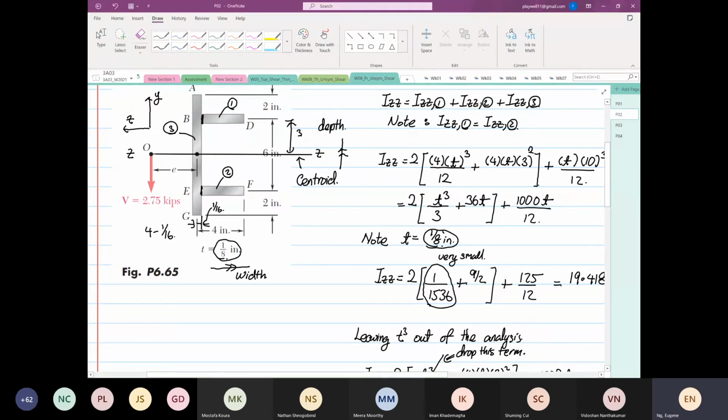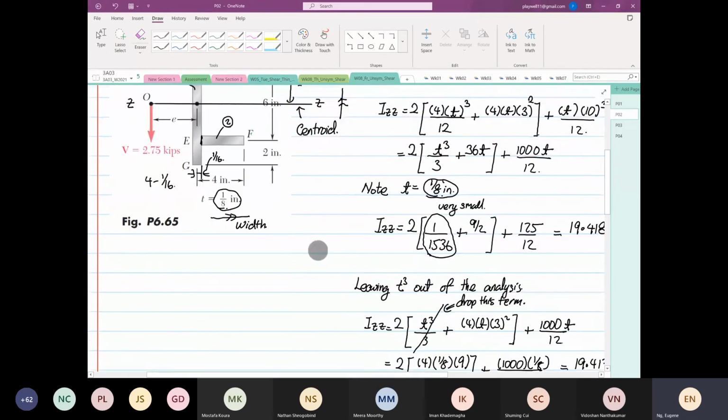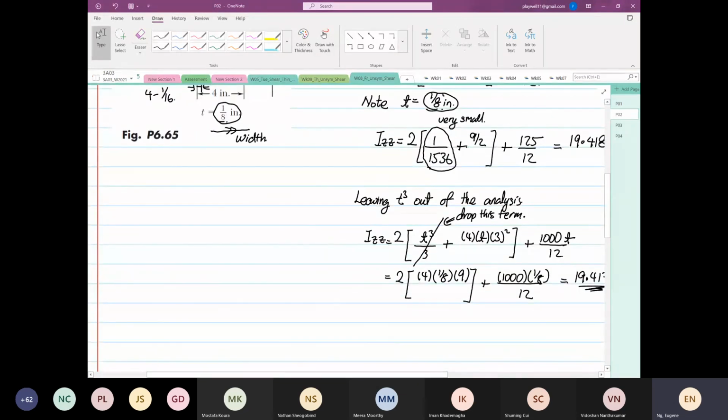Right? So in T1 analysis, what we do is we do not consider the thickness at all. I repeat, we do not consider thickness. What we consider is just basically lines. Literally, we consider the structure as just lines, like this. Does that make sense? So now we're going to find the second moment of area of these lines.